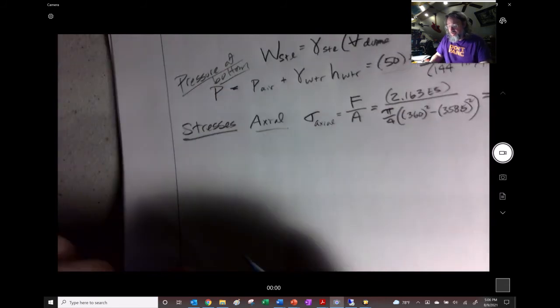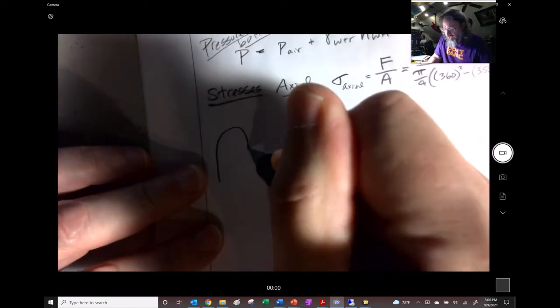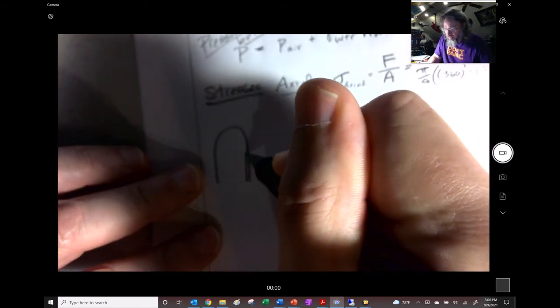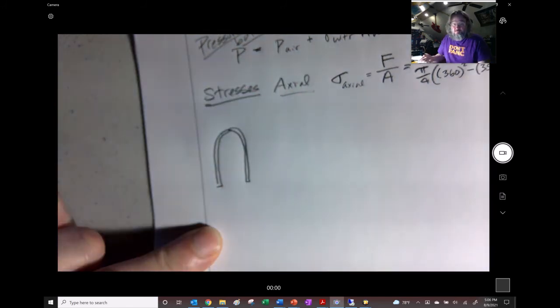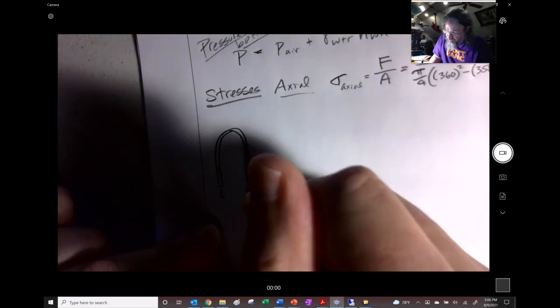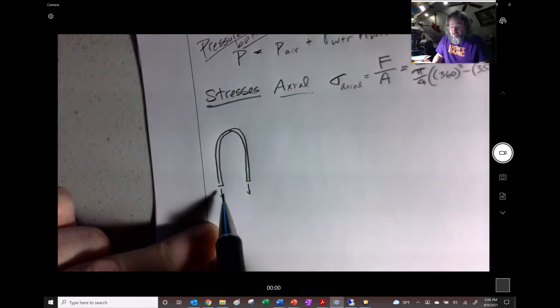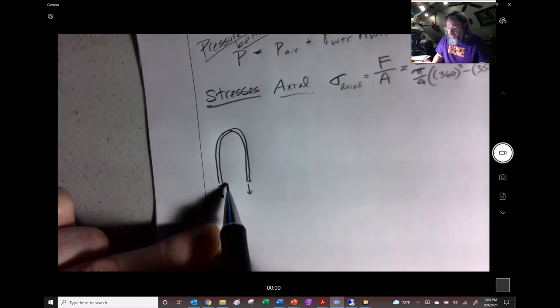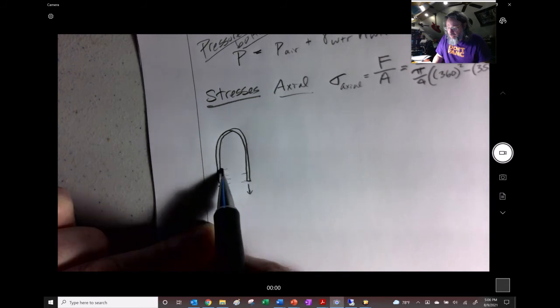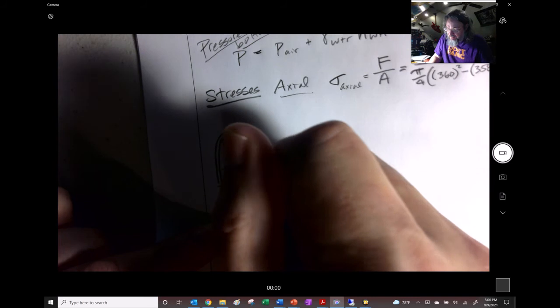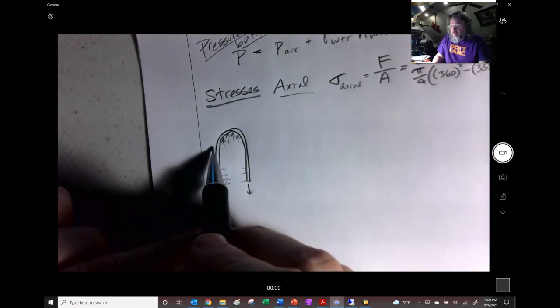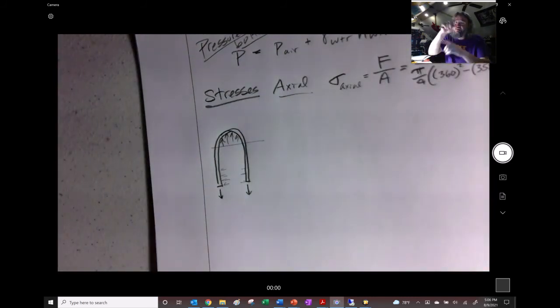You could even, if you want, draw out just the steel by itself, a cross section of it, like this right here, and think about that, right? The longitudinal stress is really that stress times the area through the thickness of the thing, and you could think about the loads of the water coming. They're all coming out and pushing out this way, but it's really the pressure of the air that's acting up across this cross section, right? And it doesn't matter that it's a dome.